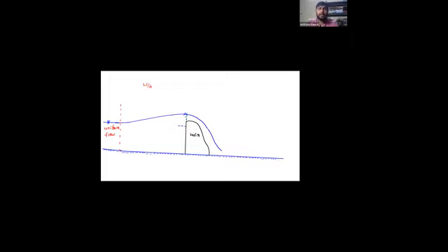My dear, here kinetic energy means it is represented by velocity. Potential energy means it is represented by the depth of flow. So on the upstream side of an obstruction, velocity will decrease and the depth of flow will increase. Yes. Now, when I open the gate, the water will fall over here. Once the water falls from a certain height, the velocity of flow would be more, the kinetic energy is going to be more.